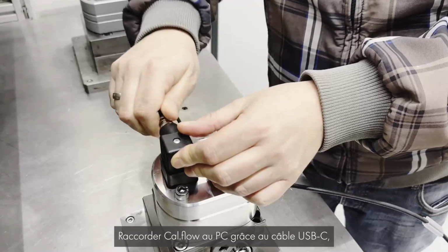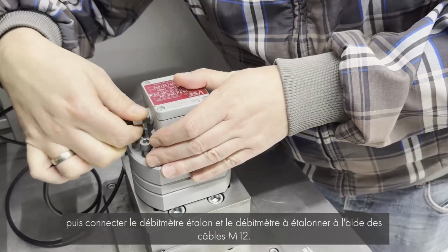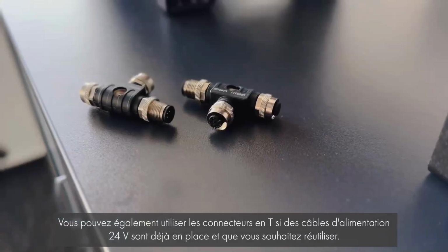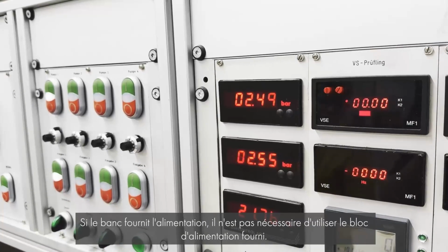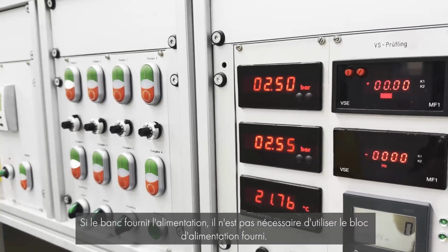Connect the Cal.flow to the PC using the included USB-C cable, and then connect the master with the included M12 cables and also the test flow meter. You can use the T connectors also if you have existing cabling with 24 volt power supply where you want to pass your signals to. If you get the power supply from the bench, you can omit the power supply that is included with Cal.flow.